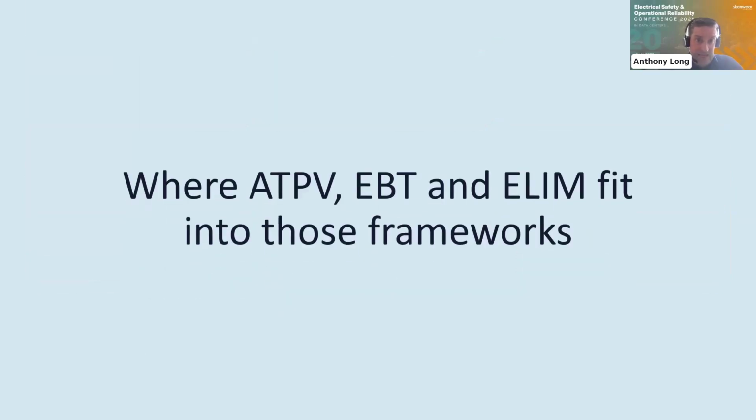So where ATPV, EBT, and ELIM fit into those frameworks. As I've mentioned a few times through this, this is just a bit of a recap. You may be quite fine with using ATPV fabric. You may need to layer up a lot with the particular work that you're doing. So it may be worthwhile looking at an EBT garment for either an outer or an inner, depending on the work that's being carried out and depending particularly on the climate.